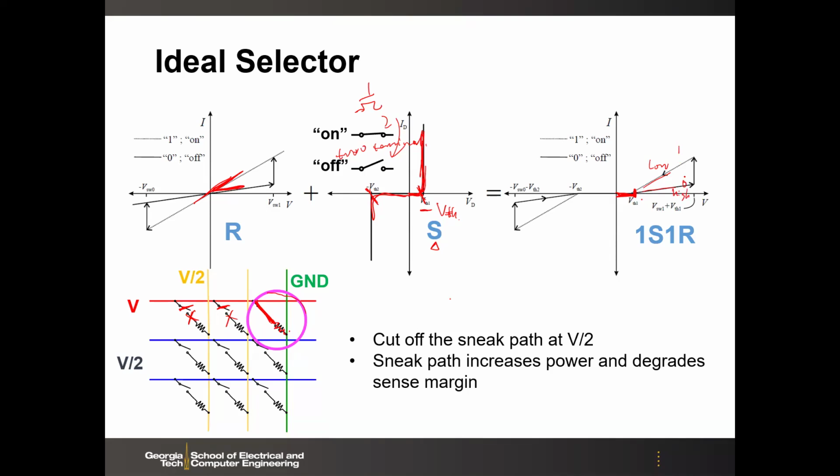Okay. So this is like your write voltage to switch from, let's say, low to high, or high to low resistance states, or let's say set from 0 to 1. Then you're going to read somewhere here, right? You can still detect two currents at lower VR, the read voltage, but this VR has to be higher than the threshold for this selector, VT.